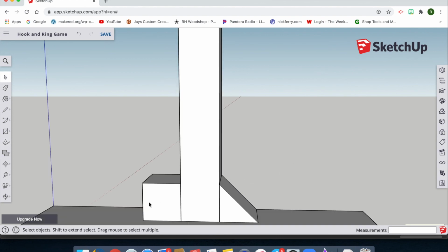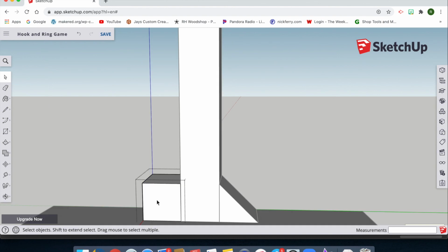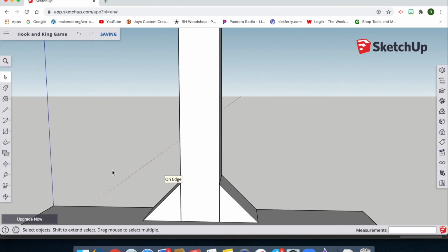And then come over here to this side, double click and do the exact same thing, just opposite. This time you're going to go from the top right hand corner to the bottom left hand corner. P for push pull, click, push back, click again, space, click out of the box. Go ahead, pause the video and do that. And don't forget guys, if you need to rewind this video, rewind it and do it as many times as you need to do it.